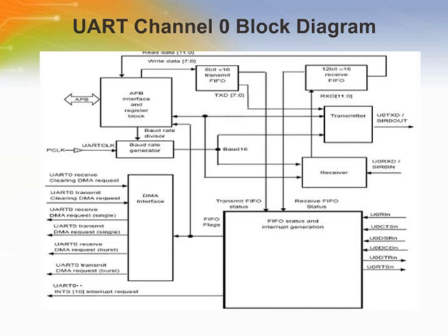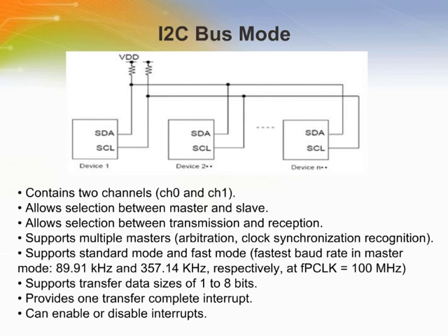Transmit logic. The transmit logic performs parallel to serial conversion on the data read from the transmit FIFO. Control logic outputs the serial bit stream beginning with a start bit, data bits, with the least significant bit, the LSB, first, followed by the parity bit, and then the stop bits according to the program configuration in the control registers. This module also supports Toshiba's proprietary data format called Free Data Format.